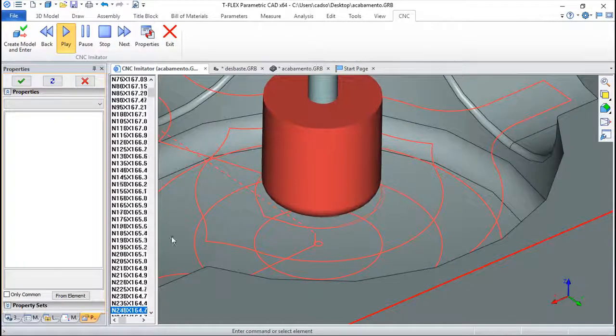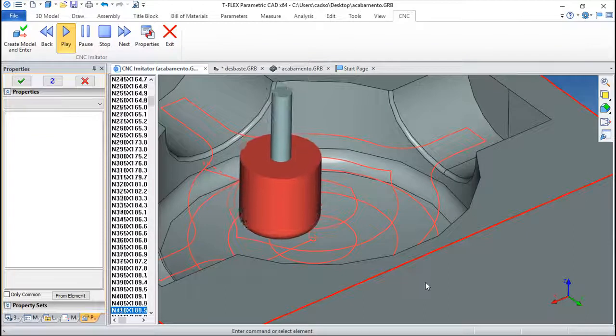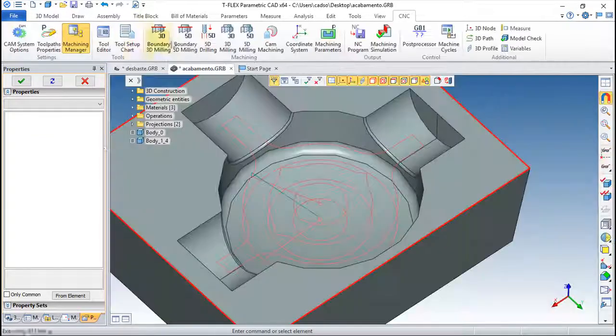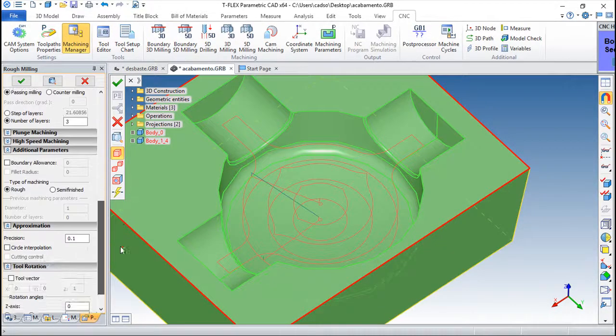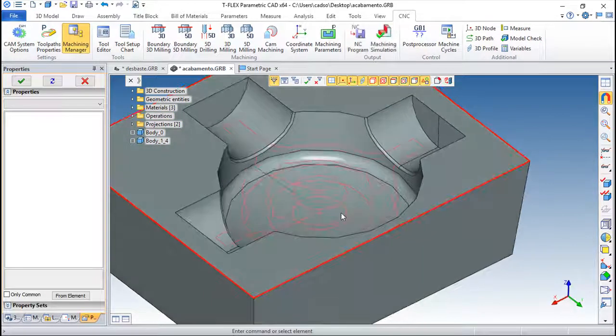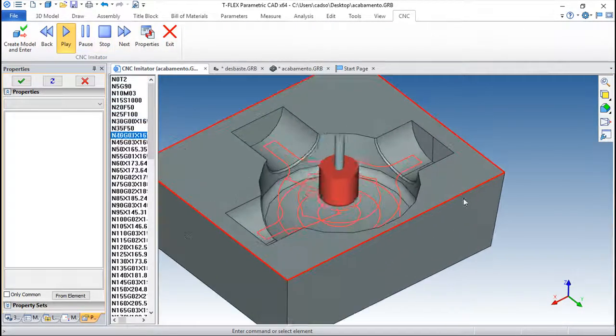So you see that it has a lot of points. Okay, and the tool moves very slow. You know this parameter, we mentioned it already below, that we can make this a little lighter if we do this circle interpolation, and you can see this, it seems the same toolpath, but on the simulation you'll see that it is much lighter.